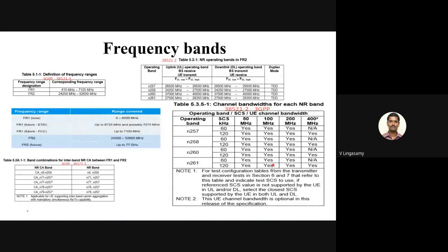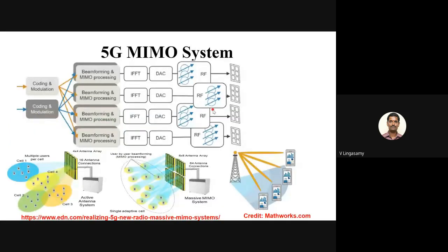Okay. Next is frequency bands. Some of the defined frequency bands. In 3GPP basically, you can see that FR1 is 410 megahertz to 7125, but it is now revised to more than 7.5 gigahertz basically. Some of the bands are widely used across the world, and these are some of the millimeter wave bands which are being used. And you can see the carrier aggregation bands. So you see the 3GPP specification. We will talk about this later. The specification will dictate which band is to be used in which region. It is very clearly mentioned, and that's what we have to follow.